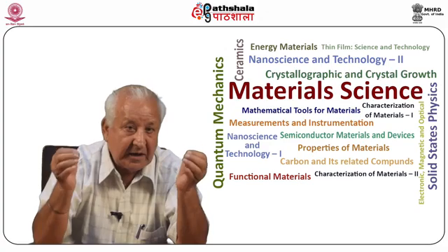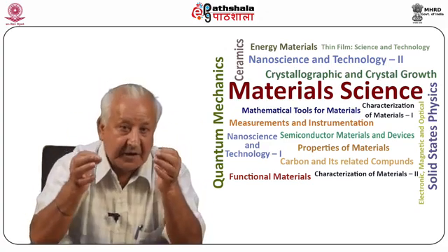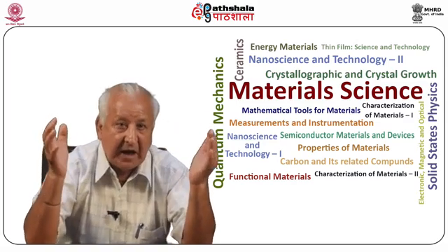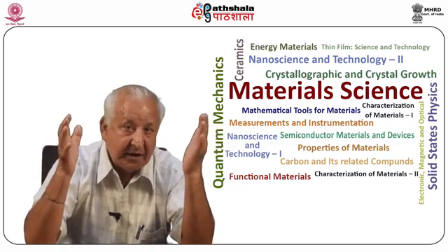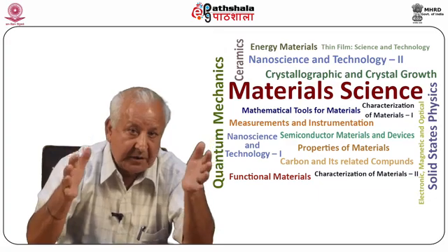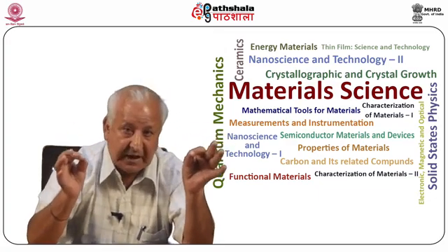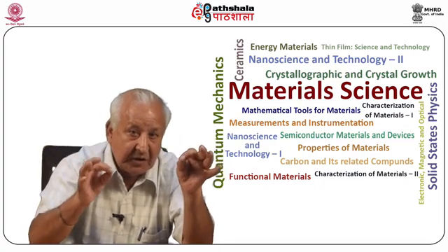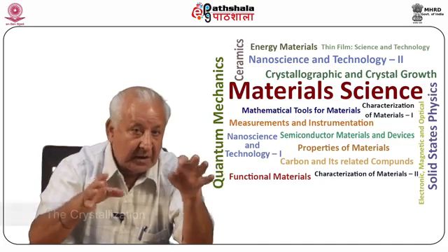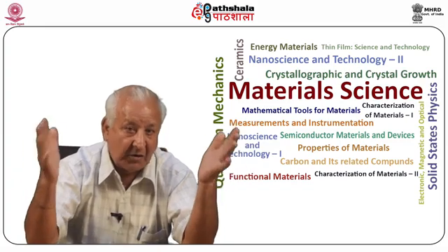This crucible is then lowered from the upper into the lower part of the furnace over a period of several days. The lowering is done with the help of an electric motor and reduction gearing system. On lowering, since the tip of the crucible enters the lower furnace first, the fluorite will start to crystallize there. It is how the nucleation problem is overcome. With the continuous lowering of the crucible, the crystallization proceeds until all the contents get solidified.